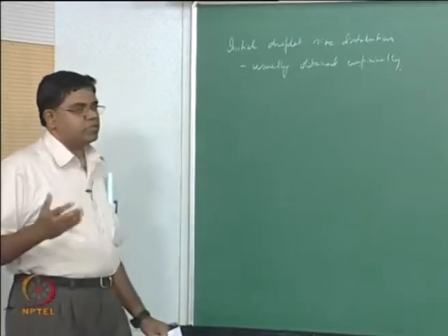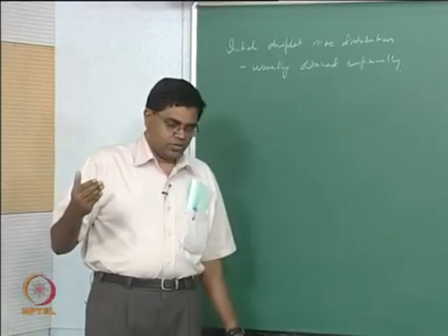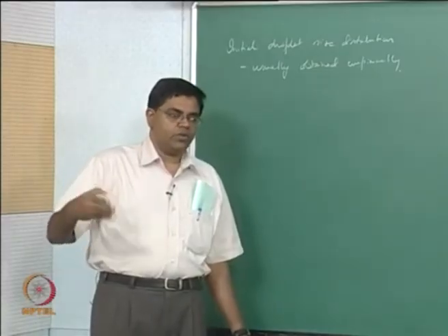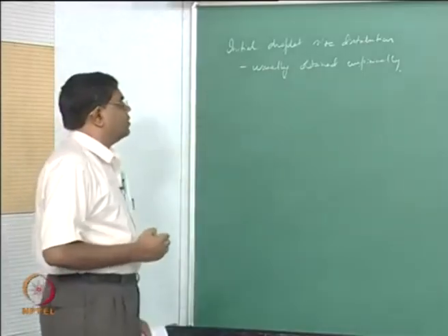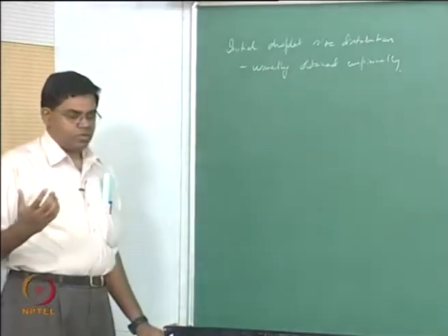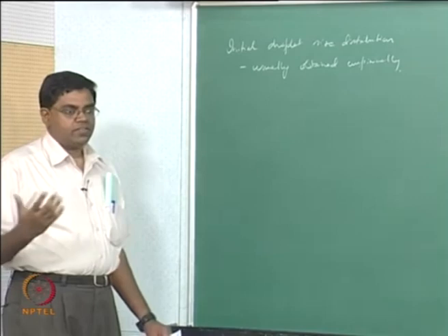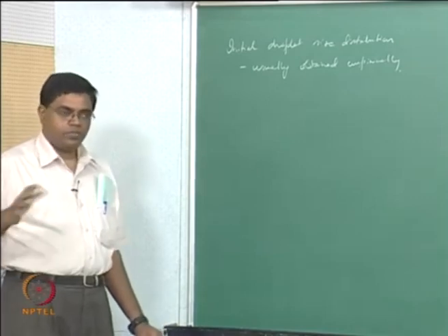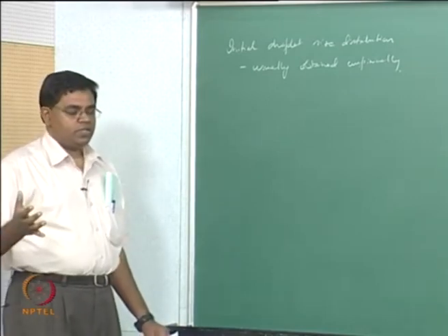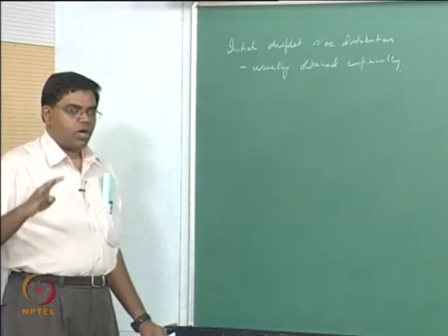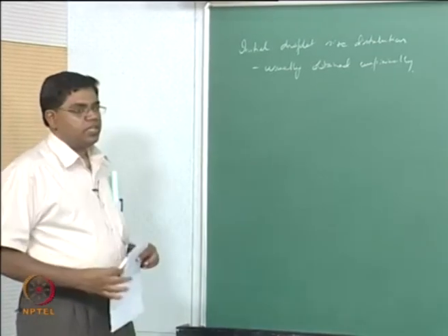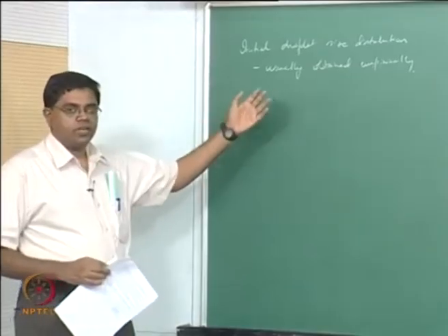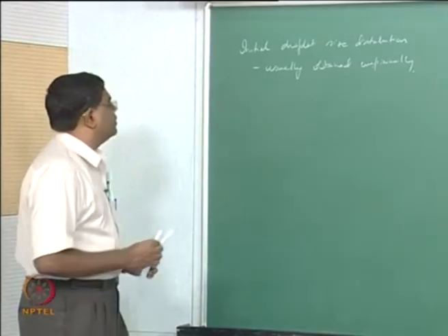But of course there is a lot more that needs to be done computationally to be able to predict droplet size distributions accurately. At the moment I think they are mostly used for design of atomizers from a qualitative viewpoint, like for example if you change some parameters, how does it affect the droplet size distribution, but they are always benchmarked and calibrated against experimental data.